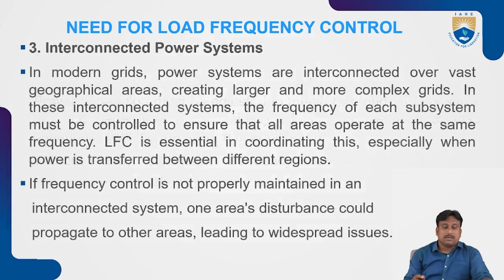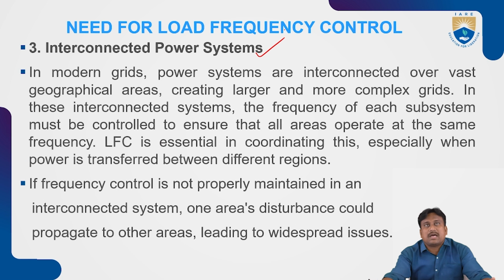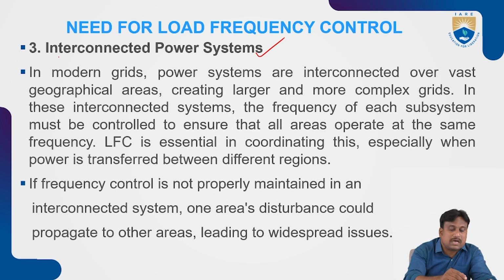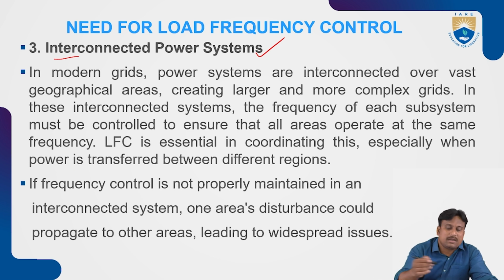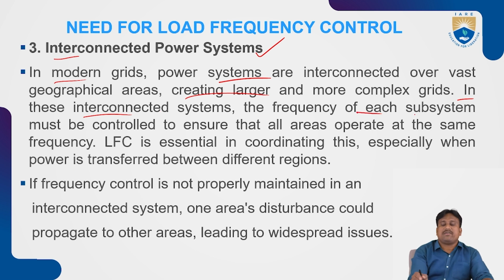Next, interconnected power systems also influence the load frequency control approach. With modern grids and the latest developments, power systems are interconnected over vast geographical areas, creating larger and more complex grids. In these interconnected systems, the frequency of each subsystem must be controlled, to ensure that all the areas operate at the same frequency.